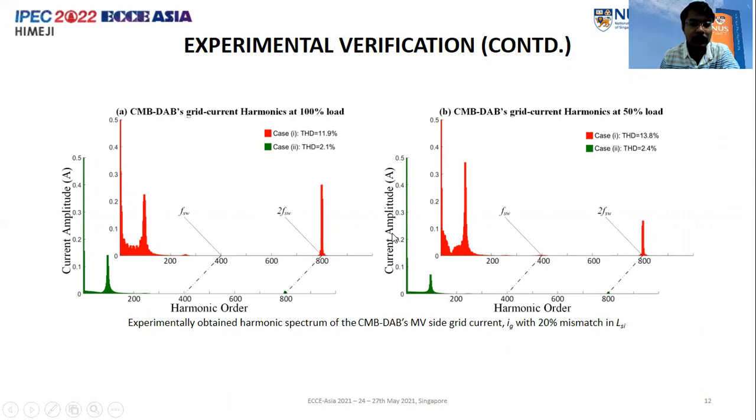Because there is a single peak in the switching frequency harmonic spectrum, once the power balance controller is successful in eliminating that, most of the major harmonics can be eliminated, and there are no lower order harmonics remaining.